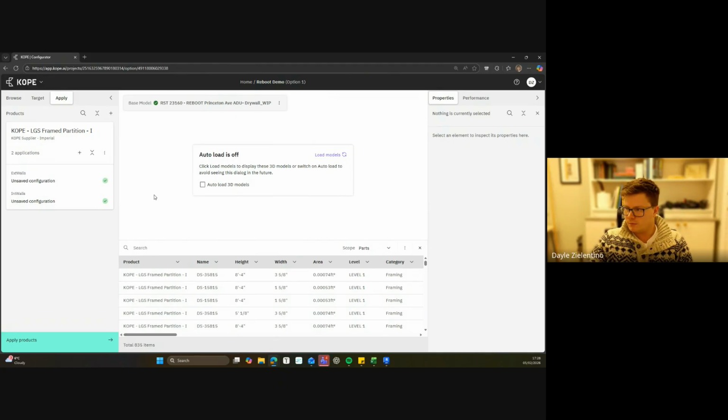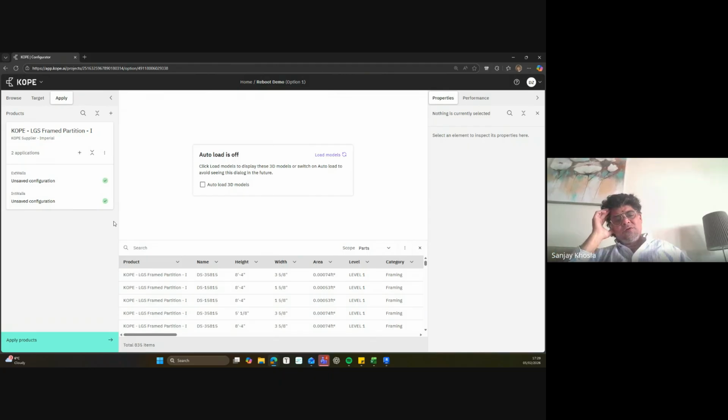And that would say, actually, if you go with a lower gauge but a higher stud count, that higher stud density, yes, you have more steel, but that steel is so much cheaper because of the thinness of the steel and the gauge, that overall that works out cheaper. So whilst you have more studs being placed, it is a lower cost gauge, which means that in the round, because you have fewer panel types, that ends up cheaper. Yeah, what you just described, sorry, go ahead. So that's what these studies are.